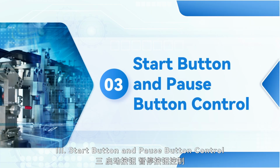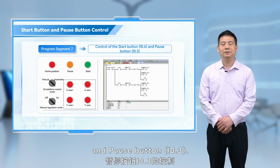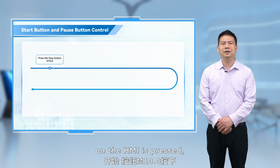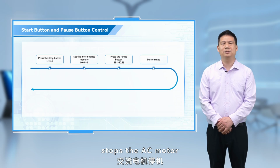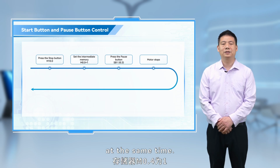3. Start button and pause button control. Program Segment 7 involves control of the start button, I0.4, and pause button, I0.3. When the start button, M10.0, on the HMI is pressed, the intermediate memory M0.0 is set to 1. Pressing the pause button SB1, I0.3, on the panel stops the AC motor, and sets the intermediate memory M0.4 to 1 at the same time.